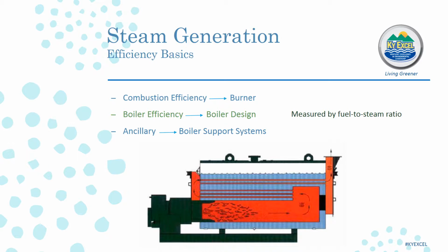Boiler efficiency is measured by fuel-to-steam efficiency, basically BTU input versus BTU output, ultimately reflecting the amount of heat transfer from the fuel source to steam or hot water. Fuel-to-steam efficiency is a better measure of overall efficiency because it takes into consideration the effectiveness of the heat transfer, as well as the radiation and convection losses in the boiler shell. Published efficiency is based on 100% of the boiler's rated capacity in a steady state and often does not take into consideration cycling and purge losses, along with other operating variables by application that will reduce actual efficiency.